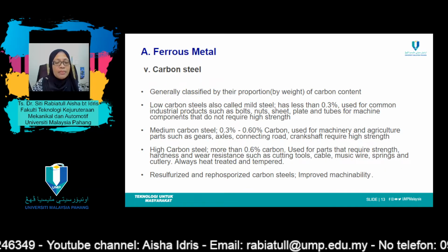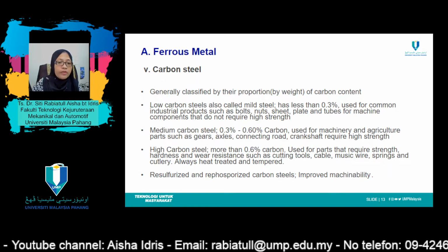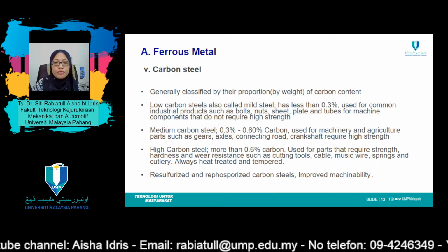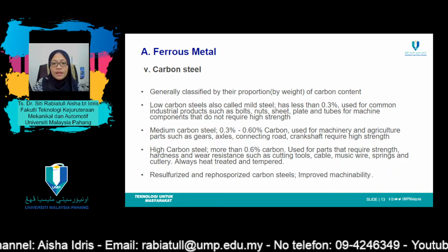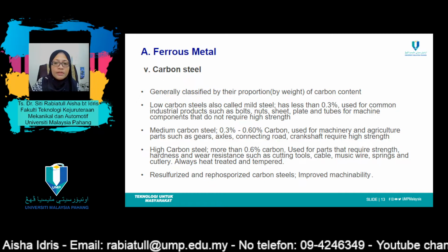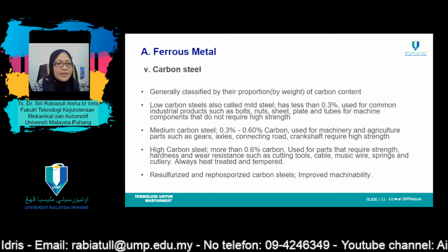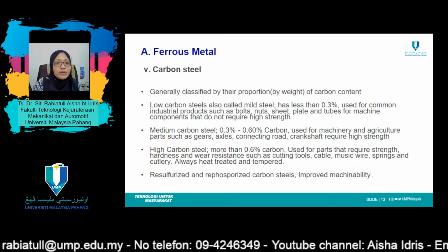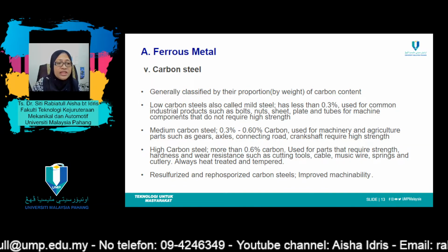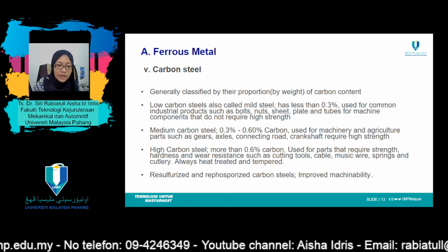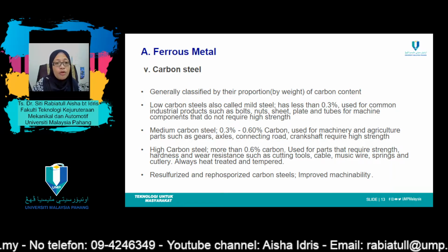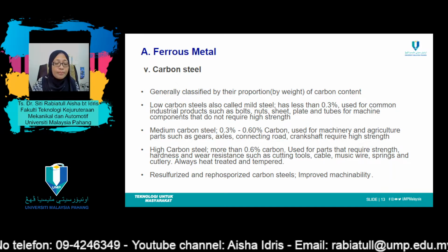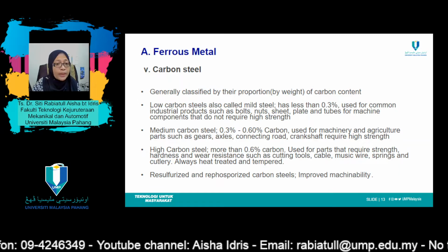for medium carbon steel, the concentration of carbon is between 0.25 and 0.6 weight percent of carbon. These alloys may be heat treated by austenitizing, quenching, and then tempering to improve the mechanical properties. They are most often utilized in the tempered condition, having a microstructure of tempered martensite.